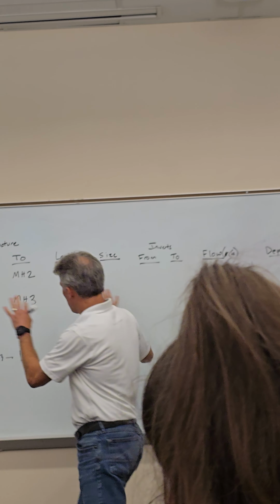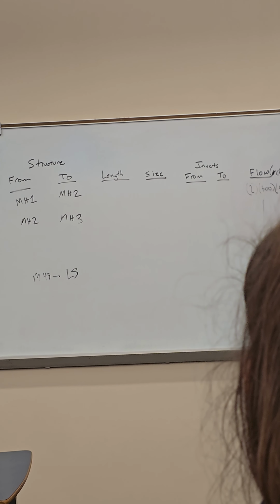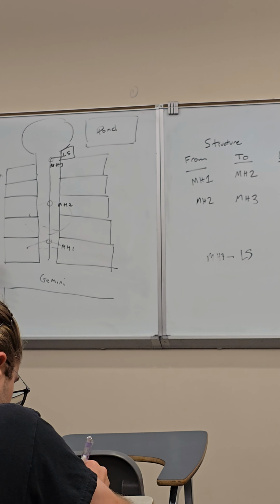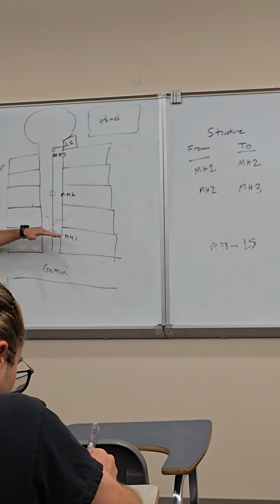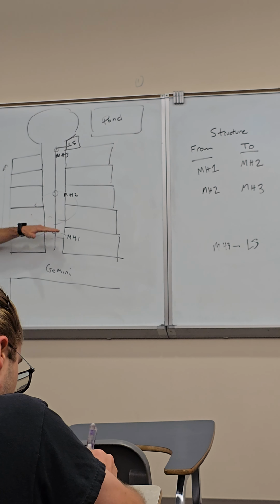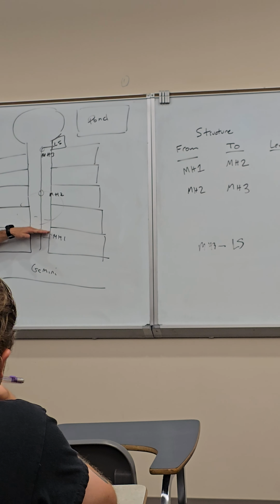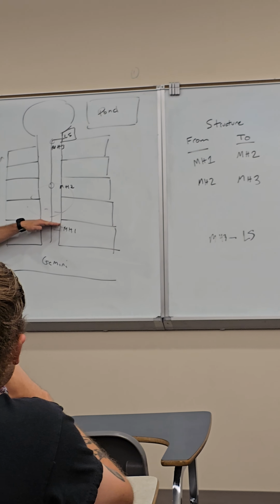So let's talk about some other pieces. Now, we didn't design the road, right? We didn't create a profile of the road, so you don't really have any proposed elevation. So what I want you to do is just assume the existing contours are the elevations. So locate your manholes and estimate the elevation of the top of your manhole based on whatever existing contour you have.